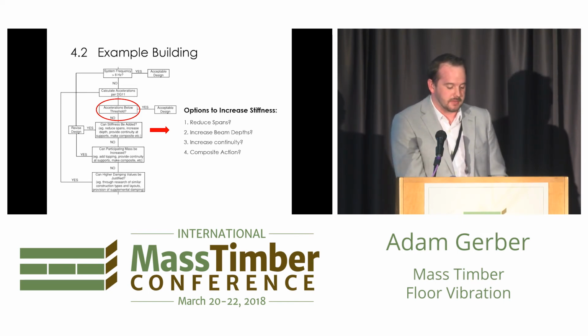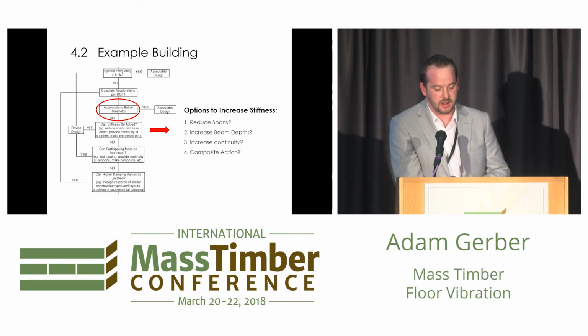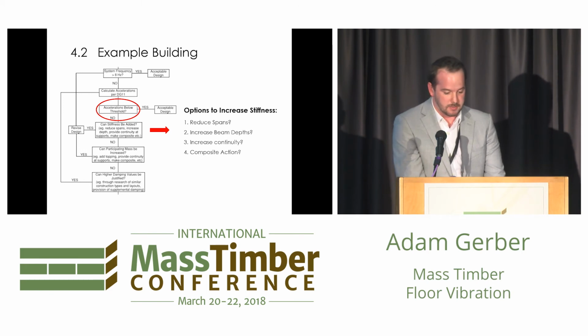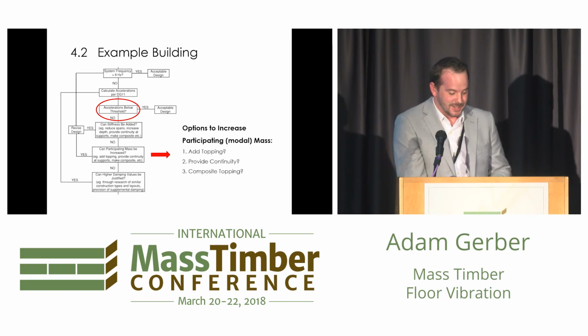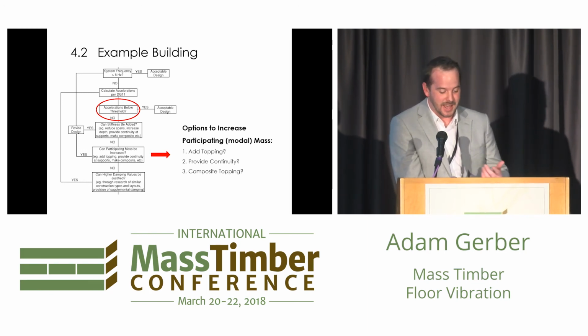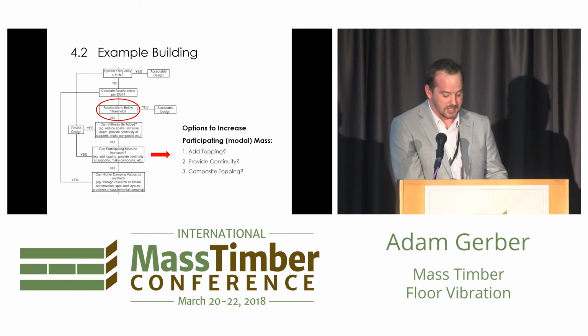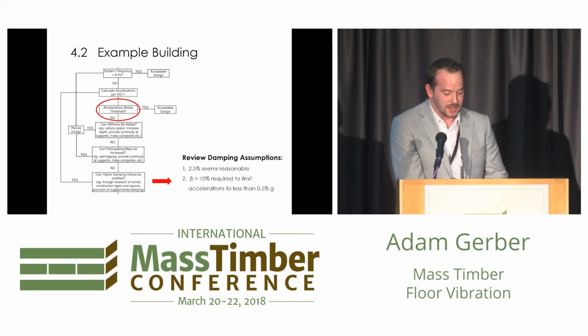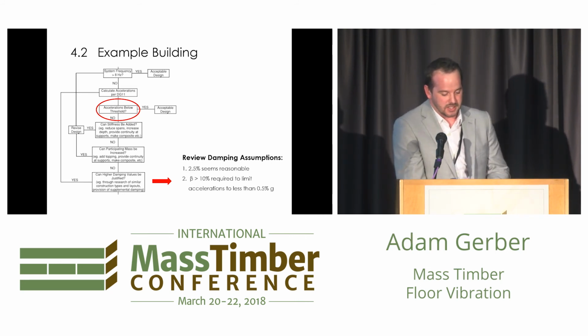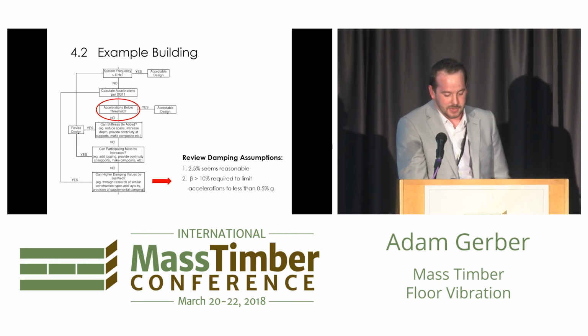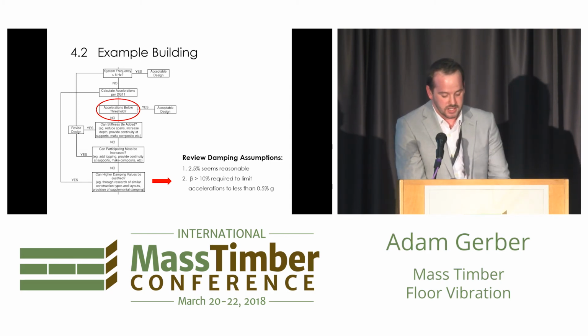So going back to the team, we looked at, are there options to increase stiffness? Can we reduce the span, increase the beam depth, increase continuity, find a way to introduce some composite action? The answer turned out to be no. So we went on to the next. Can we add mass? Can we, again, make a composite topping perhaps? Again, it was no. This is all post-tender, so the pricing was fixed and nothing was free, it turns out. And then reviewing damping assumptions, we went in with 2.5%, but in order to bring it down to where we needed to be, we'd have to justify something in excess of 10%, and that's just not realistic.